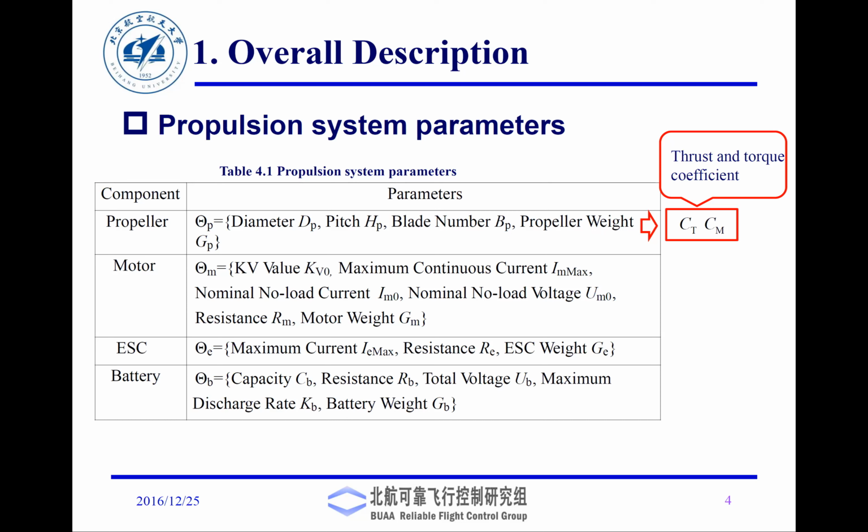In my personal experience, if you look at quadcopters, I do not know if that problem is as severe, because I have not seen a very commercial quadcopter that is used to carry payload or humans. Vortex ring state can happen in the case of helicopters. But when we are talking about small drones, usually I haven't seen the vortex ring state instability. If the quadcopter has to fail, it actually fails before the vortex ring state appears.